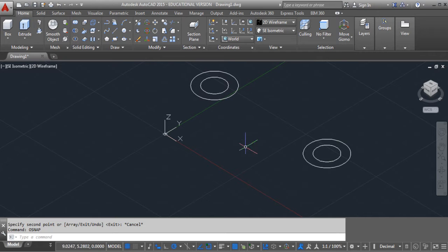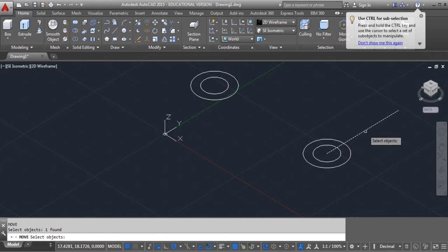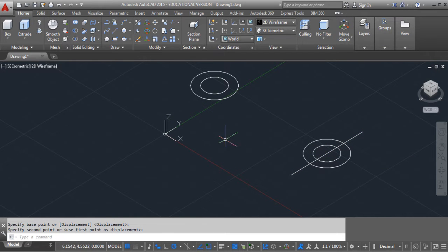So now that we've got our circles, we want to know where we can draw our lines for our tangents on our circles. So we will go ahead and click on line. And we will draw us a line here. And we are going to move that line down to here. See, the triangle shows us the midpoint. The square shows us the circle. So now we are going to copy this line as well. There's the triangle.